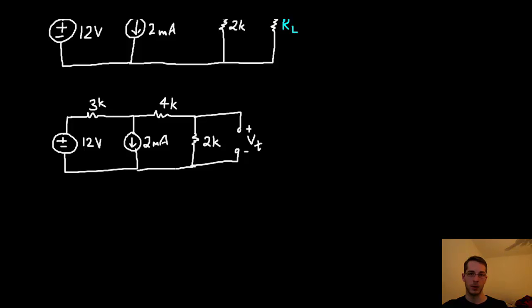I'm going to choose to use Nodal Analysis here because I can. Let's do green for this. If I say that current's going this way over here and down over here, and this is given to us as going down in the middle, this is some node Vx. Basically, we're going to use this voltage Vx, and then use voltage division to solve for the voltage over here. Let's set it up.